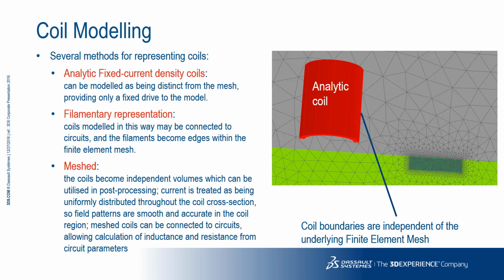In eddy current testing, the excitation of the problem will be by use of coils with, usually, an AC supply. In FEA, there are different ways of modeling coils. Which is most accurate and efficient can vary with the type of problem being solved.